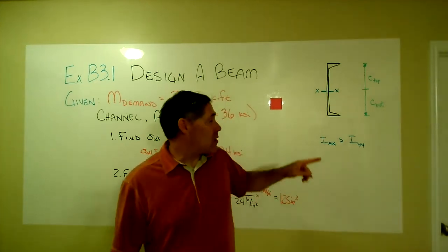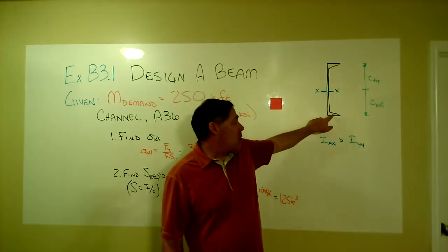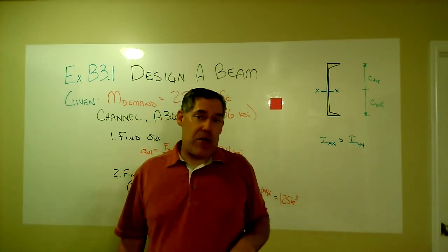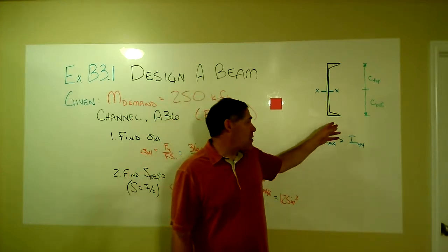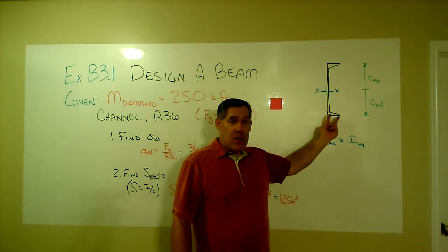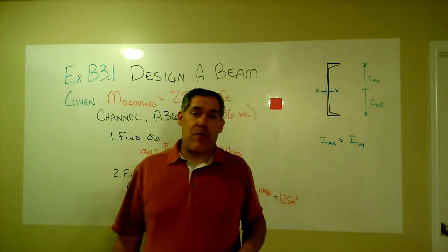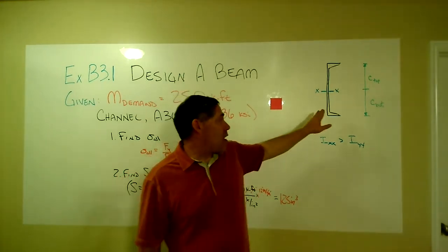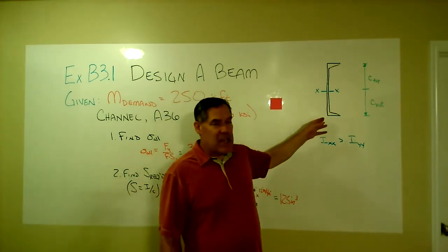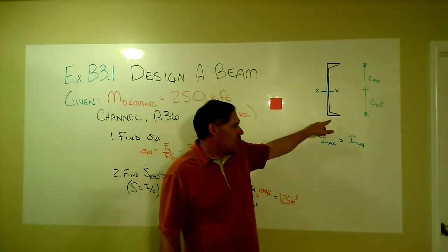It's not 1/2. There's a variety of different differences there. The primary one being that this flange outer surface and the inner flange surface are not parallel to each other. The other part that is typically different is that this flange width is quite a bit smaller compared to the depth of the cross section than you'd see in the typical W shape. So these, if you had two of these right back to each other, actually would look like a capital I, whereas the other ones sort of look like a capital H turned on its side. So we're going to take a look at this.